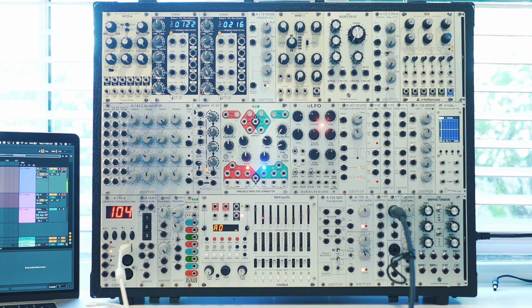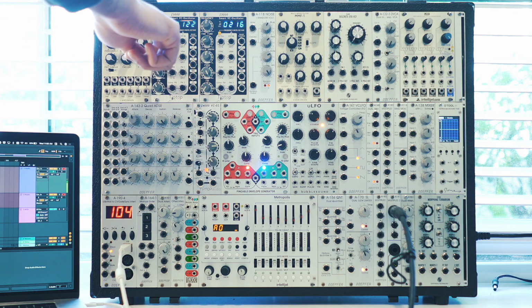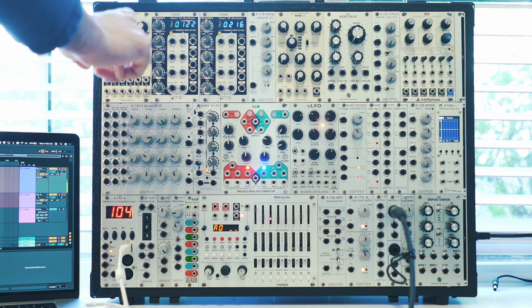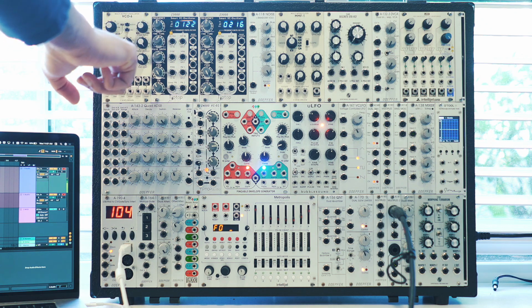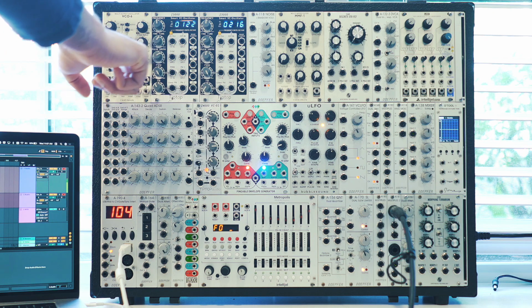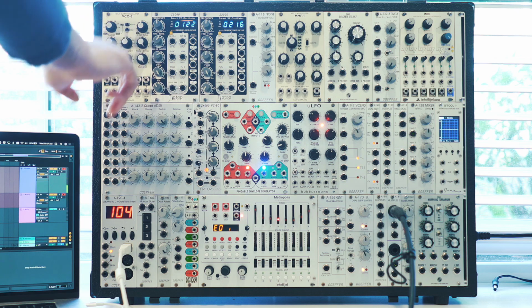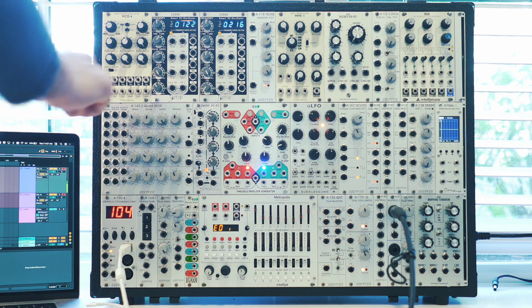Now, typically on most oscillator modules, you will have a 1 volt per octave input, like on this Z3000, but on the VCO-6, it's labeled a bit differently. They call it FM exponential. In fact, there are two labels here, FM2 exponential, FM3 exponential. Both of them would work. And you can see here, there are the two inputs for those.